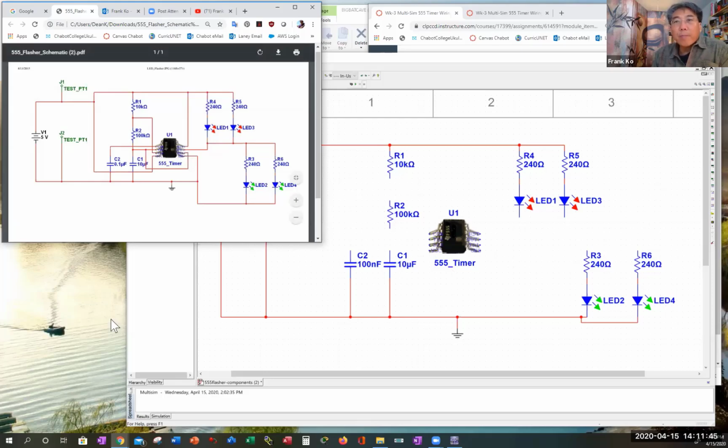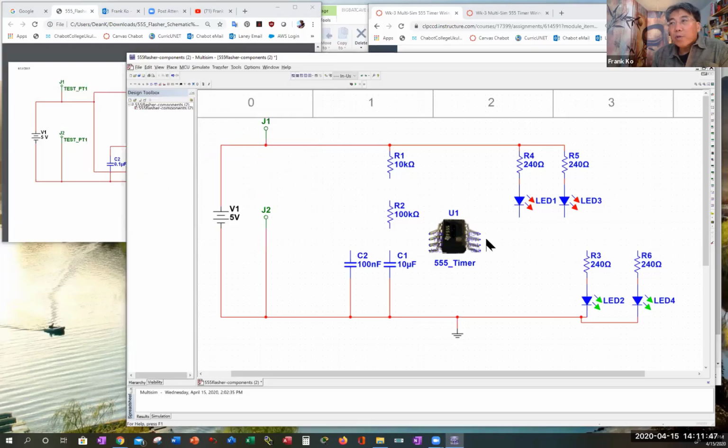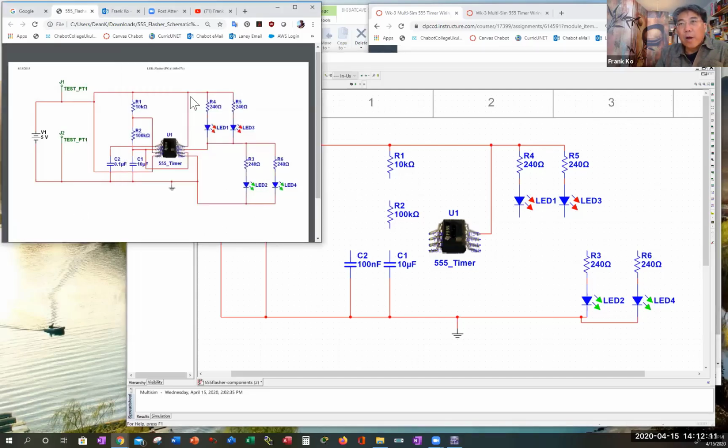So we're going to do that. Pin 1, the first pin on the right-hand side of U1. The mouse is presently an arrowhead. When I come up to that pin, it changes to a black dot. And as a black dot, I can click, click, bring it up, and click again. And now I have that connection that matches this wire here. Are we good with everything connected to the top so far?